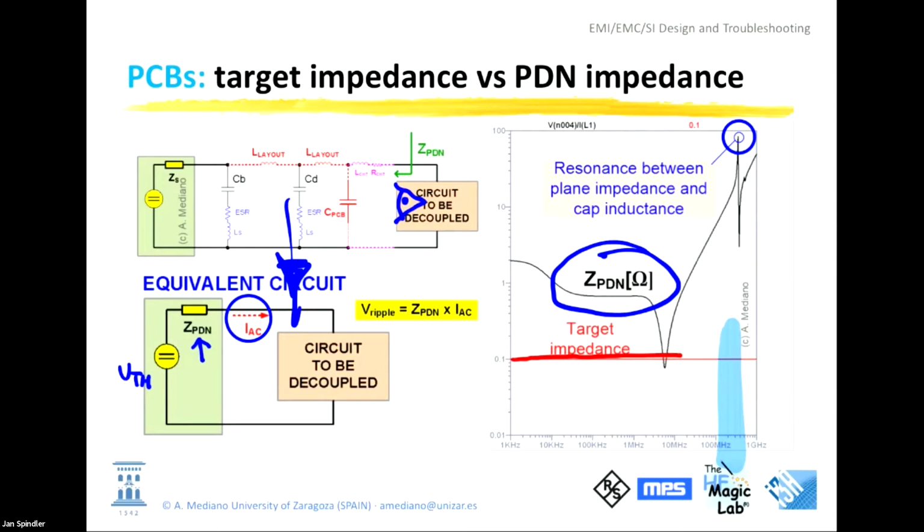You cannot do this with one capacitor. Remember the 100 nanofarad capacitor that all the people put between VCC and ground, no? Today, you cannot have decoupling with only one capacitor. You need several capacitors. In general, a lot of capacitors, because the trick in the high frequency range is to minimize the inductance, not the capacitor. And to minimize the inductance, you need to put a lot of capacitors in parallel. And in general, remember the sentence in EMI, it depends. In general, the capacitors must be of the same value, equal, not different more than 1 decade.